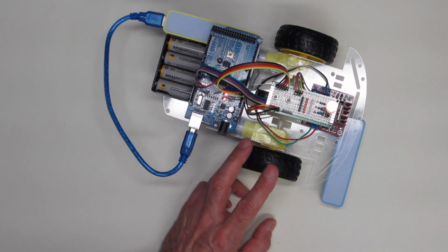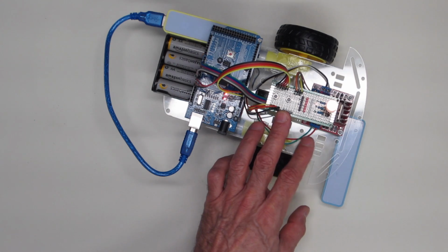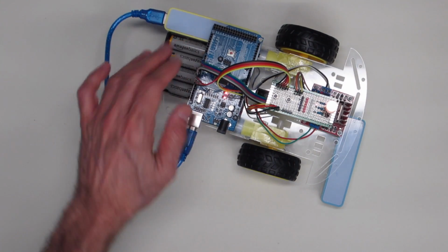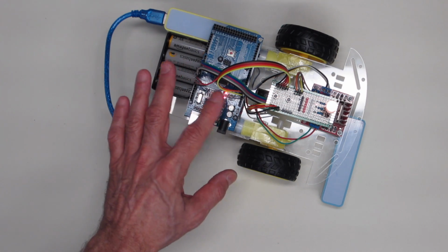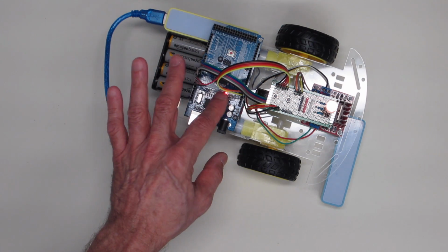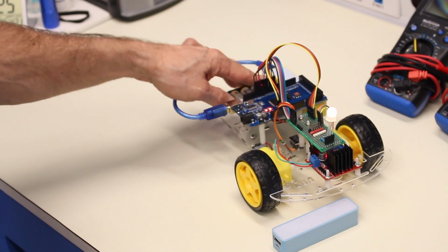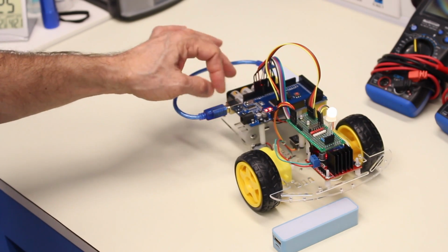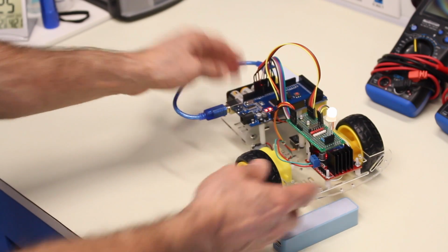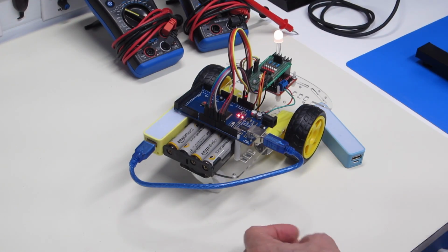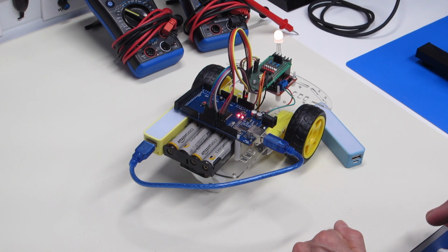These are for the servo motor I was talking about. I wanted to power the servo motor off of the 6 volt power supply and not off the Arduino's 5 volt supply, because I don't like powering servos from the Arduino power supply. And so that's why I've elected to use 6 volts and not 7.5 like I have in some of my other designs. So as you can see, it's a very basic robot design, and we'll be expanding upon this in this video and in future videos, and we're going to be making this robot run and work with XOD.